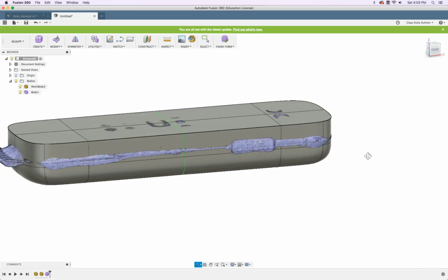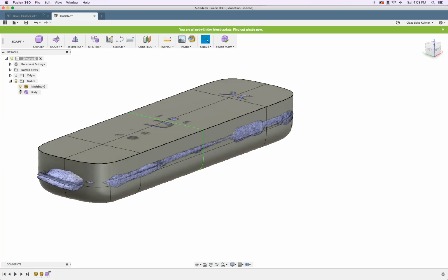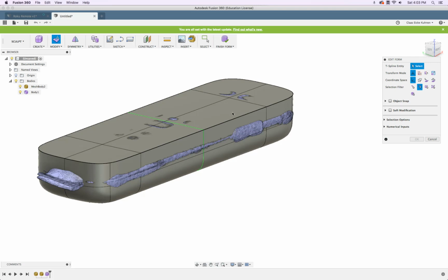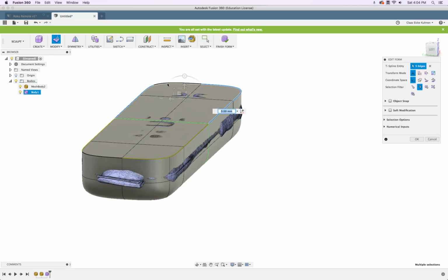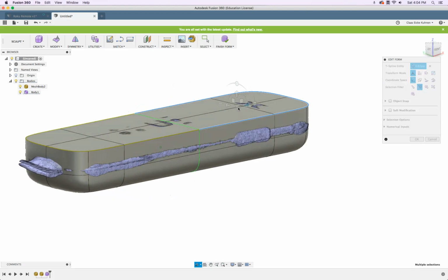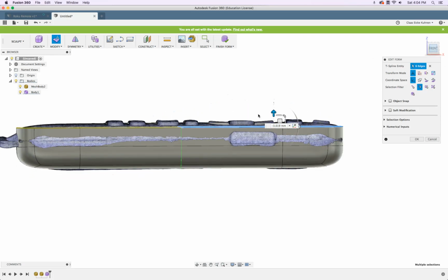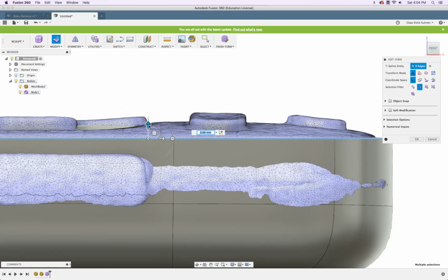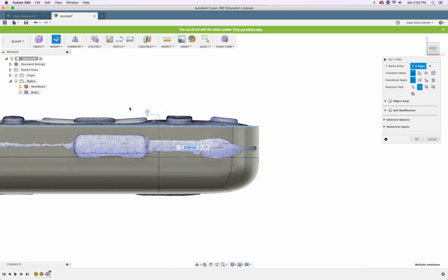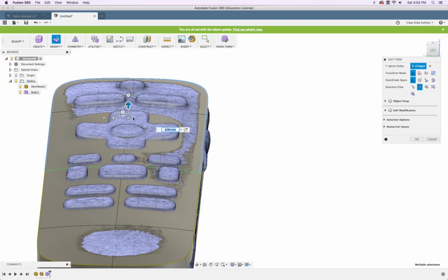So now it's nice and sharp, but it's too wide. The mesh body is still there. What we can do now is go to Modify. We're still in Edge Select, so I select this edge and this edge, this edge and this edge. Also these two. And in my first step, I will bring everything down till it seems to line up with this sharper edge on my mesh model, which looks like roughly being there. Very nice. And I have to scale everything in